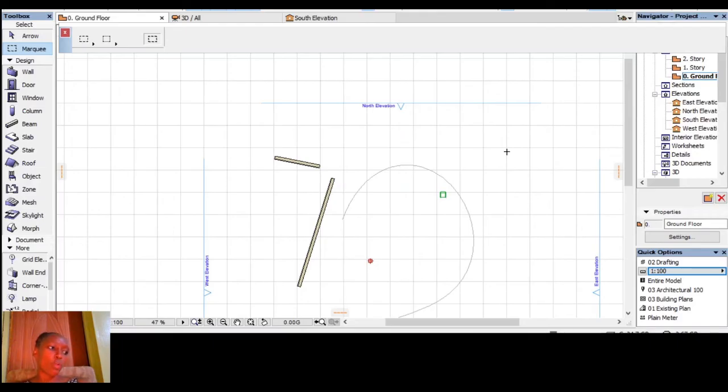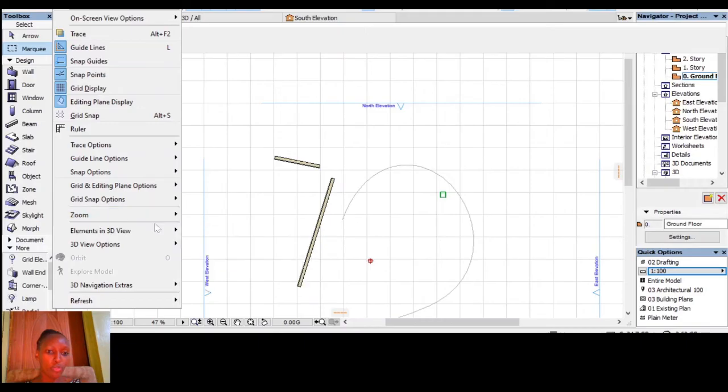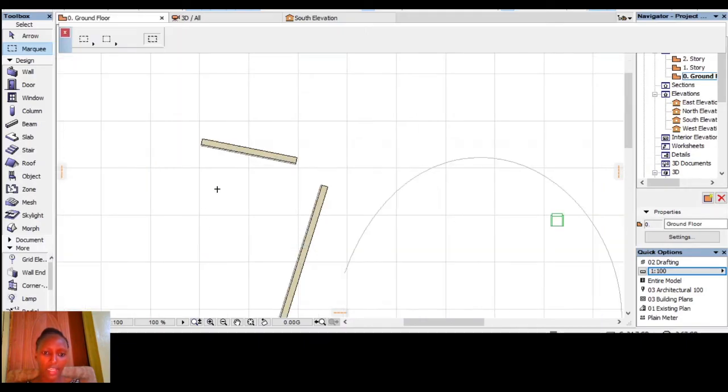After setting a scale, what you see will be a preview of the project if printed or plotted at that scale. So everything that you're able to see is this object as plotted at a scale of 1:100. To make a zoomed view match the view at the currently set scale, you'll go to View, then Zoom, then Actual Size. If we want it to be exactly 1:100, so if we are able to measure this one, it is up to scale. You see, it is actual size.